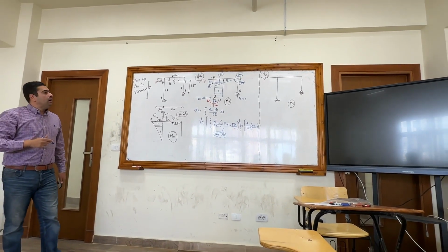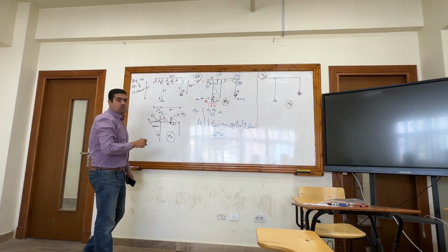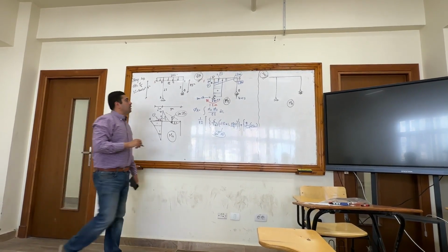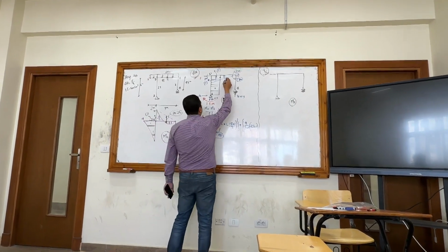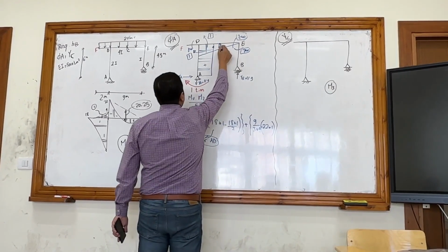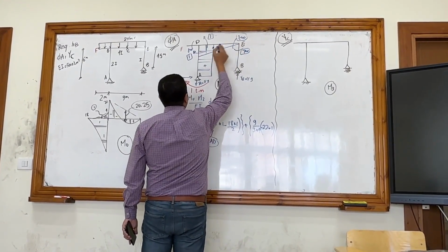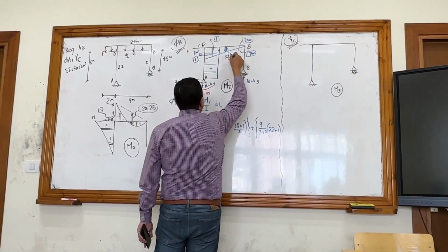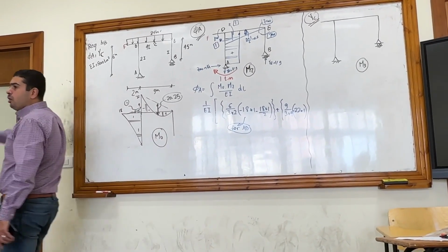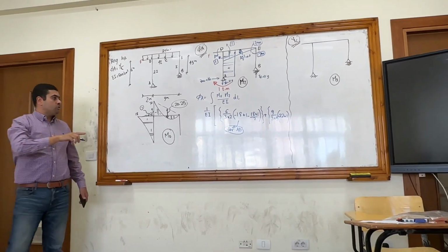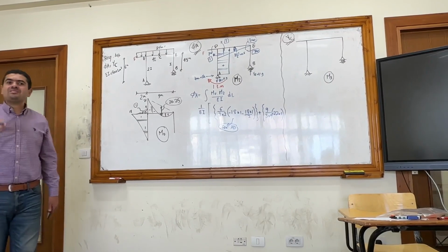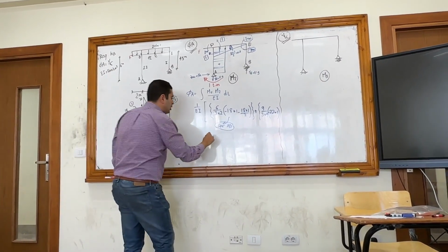Okay? What about the YCG? What is the YCG? Go to the linear shape that you are integrating with the parabola. Calculate the value at the midpoint here. Here it will be the average between 0 and 1, which is half. What about the direction of the YCG? It's downwards also. So downwards with the parabola which is subtracted, that means it's downwards. So it's the same direction. So plus.